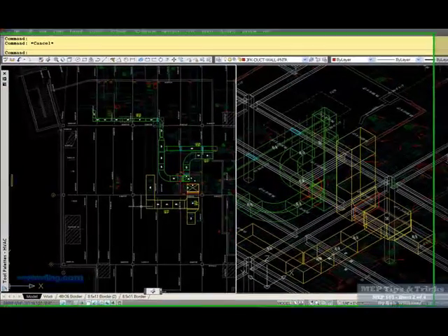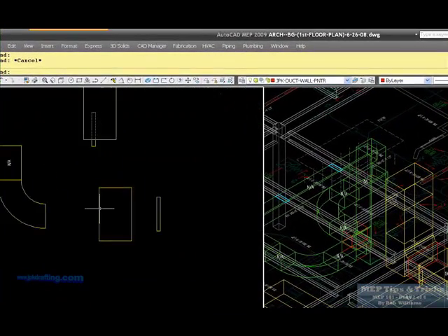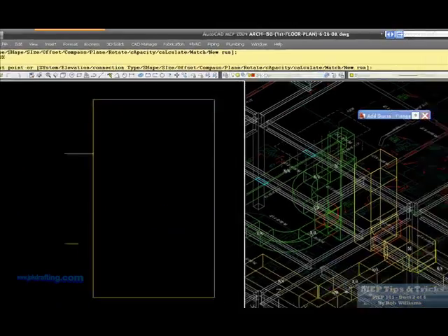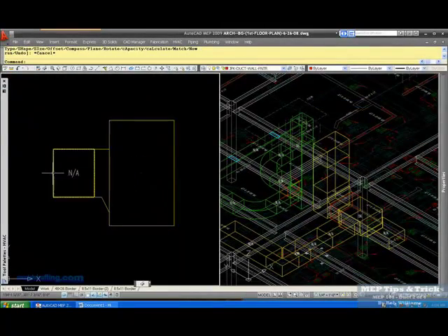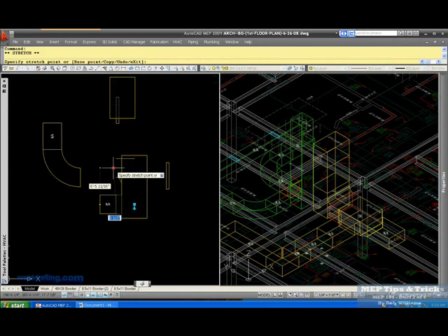And that should be it. So anyways, let's get started. We'll come over here and look at these fittings that we were working with yesterday. First one was this takeoff. By default, these are drawn out of the center, coming out of the side. And you can move them laterally this way with no problem.